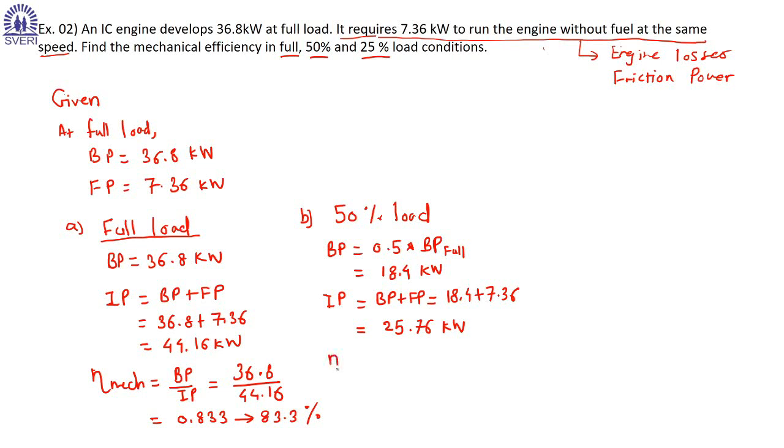Again, the mechanical efficiency will be equal to brake power divided by indicated power. So in this case, it will be 18.4 divided by 25.76.